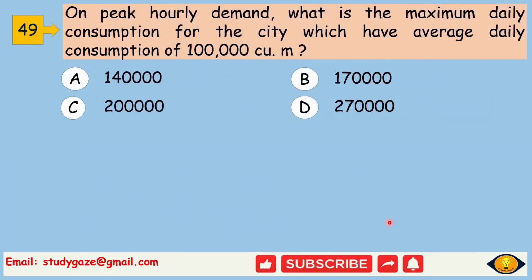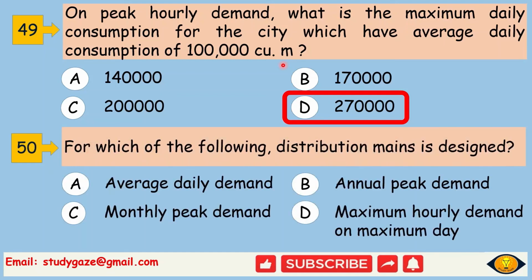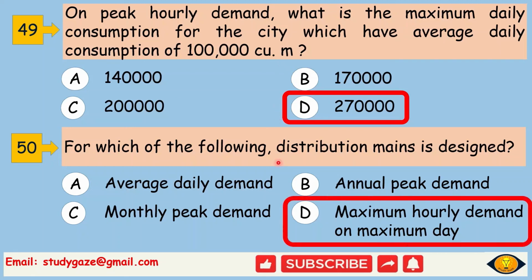Next, on peak hourly demand, what is the maximum daily consumption for the city which has an average daily consumption of 1 lakh cubic meter? So the answer will be 2.7 lakh. Next, for which of the following is the distribution main designed? So the distribution main is designed by maximum hourly demand on maximum day.